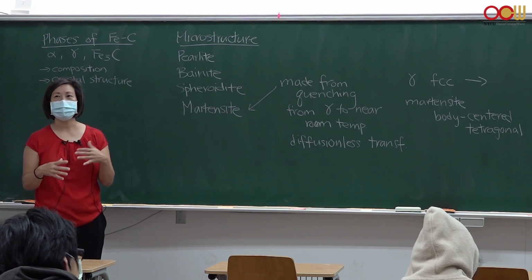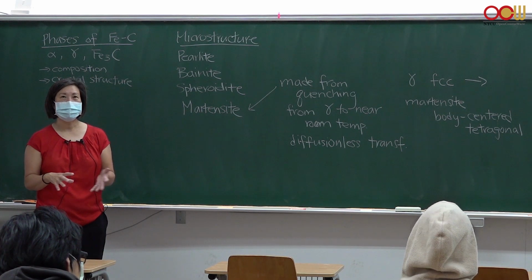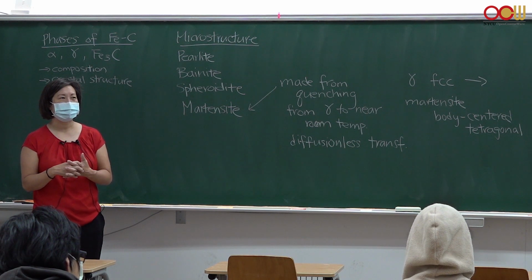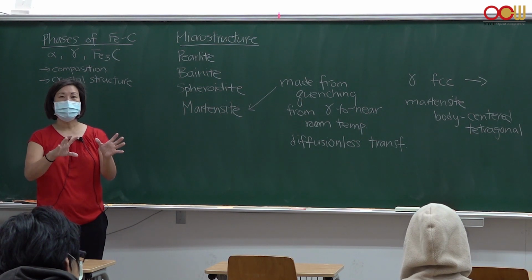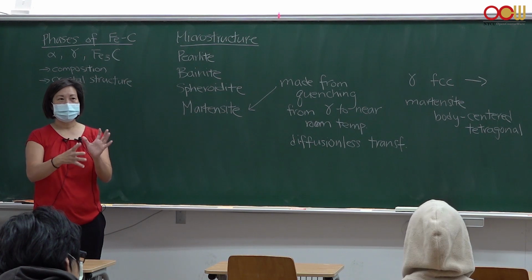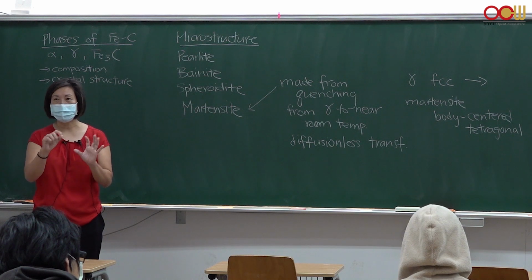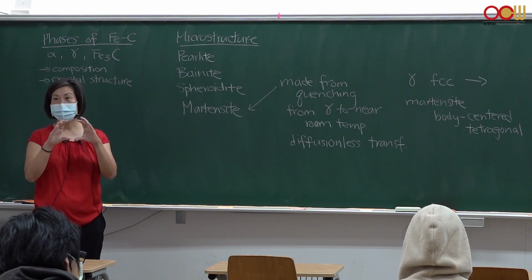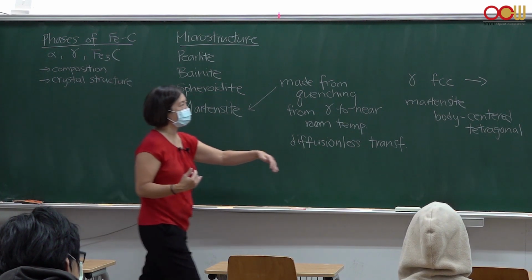That's why ceramic materials are brittle. But in this particular ceramic material, I think it was silicon nitride or silicon carbide, they made it with two very similar crystal structures. When under compression, the crystal structures can shift slightly. None of the atoms have to go anywhere, but because of that slight shift, it could change its shape, and so it could be deformed. That concept is very similar to how martensite is formed.